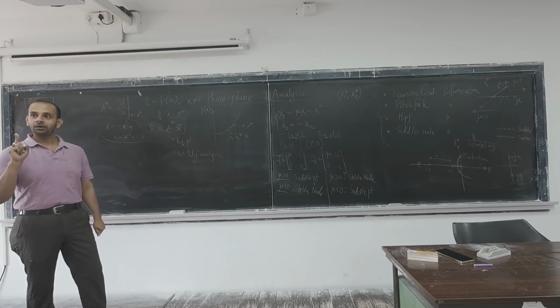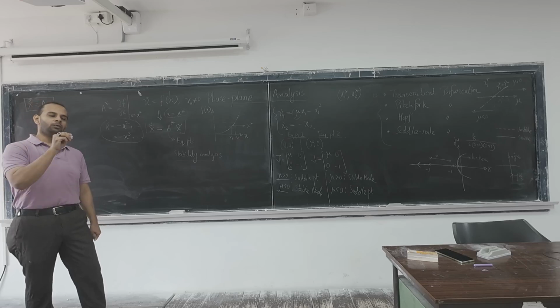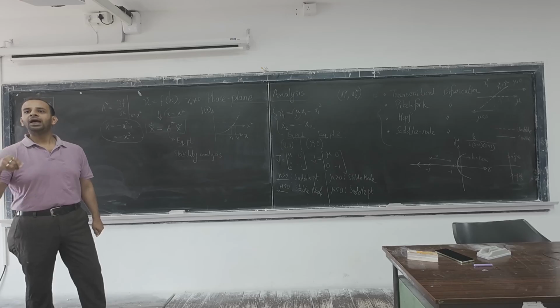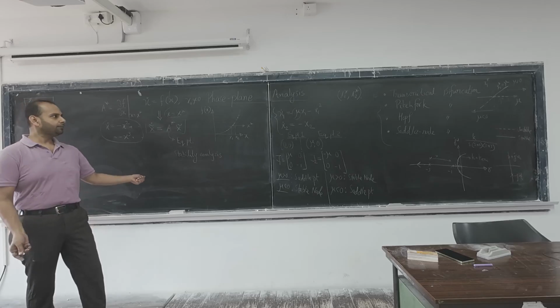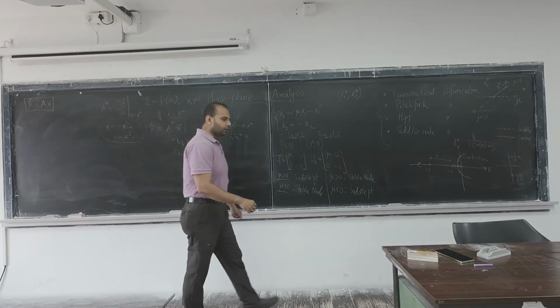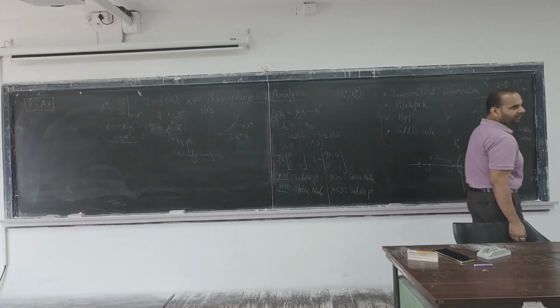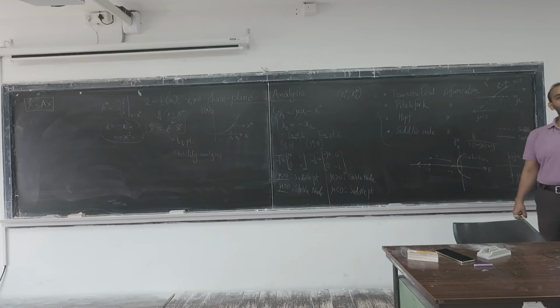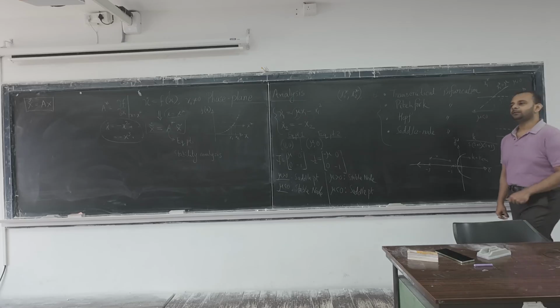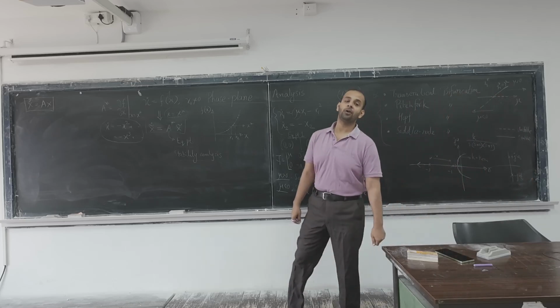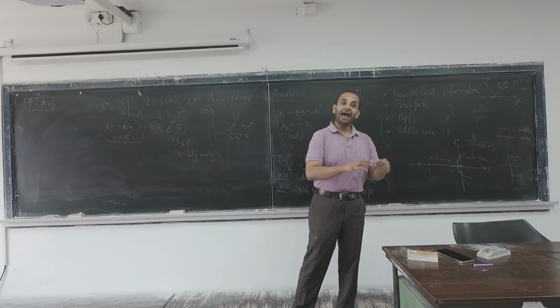Quantitative means when you are finding the actual solution of the differential equation, you are either plotting the graph or checking the individual terms in the solution, and then deciding the stability. But here we all know that solving a nonlinear differential equation is not an easy task. So instead of finding the actual solution, qualitatively we are finding the stability properties of the equilibrium points of a nonlinear system, and of course with respect to some operating points, because once again, I repeat, for nonlinear systems you cannot readily comment about stability as a whole.